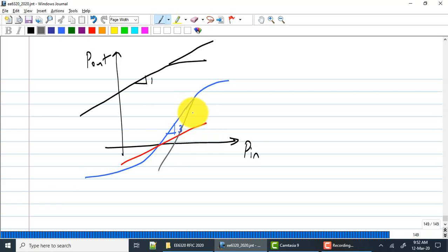In this case, you don't need to extrapolate. Most probably you will find that it is going through some parasitic capacitive path. I wouldn't worry about that. Of course, here you should not be extrapolating. The whole point of IIP3 is to extrapolate at the right point where the slope is 3 over 3. It is also possible that your circuit is doing something weird. Maybe something like this also. If it is, you need to figure out why it is doing it. All these curves are unnatural. You need to figure out why it is doing it.